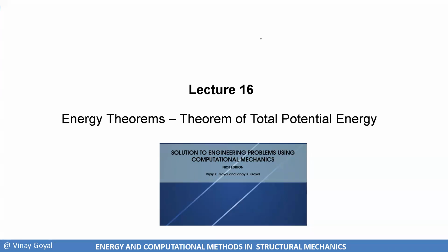Why did I do that? Because I cannot use 3D theory for everything. Imagine if I model an aircraft and every little strut I model as 3D. That'll be computationally very expensive. What if we try to model it as 1D? That'll be computationally very, very nice. And so that's why I developed the axial bar theory.